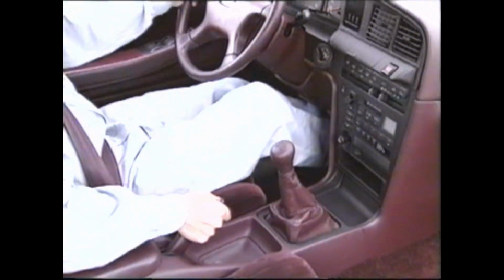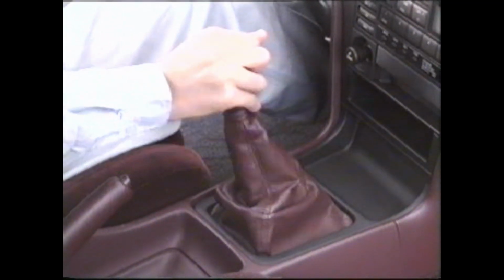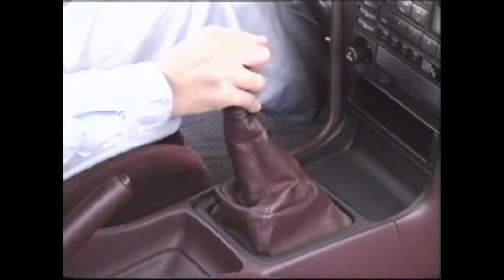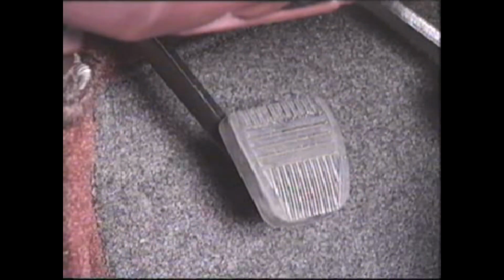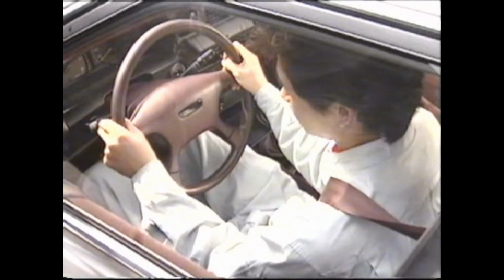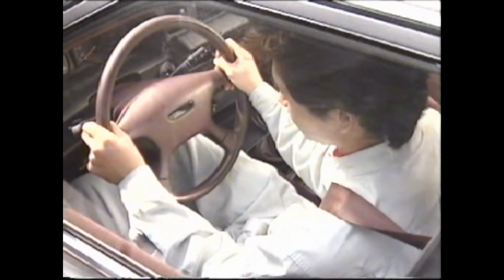Unusual sounds or noises may be heard from the clutch when it is depressed or released. Put stoppers under the wheels, depress the clutch pedal and start the engine. Put the shift lever in the neutral position and release the clutch pedal. Depress the clutch pedal again. And repeat, both slowly and quickly, to check the presence of unusual sounds from the clutch.